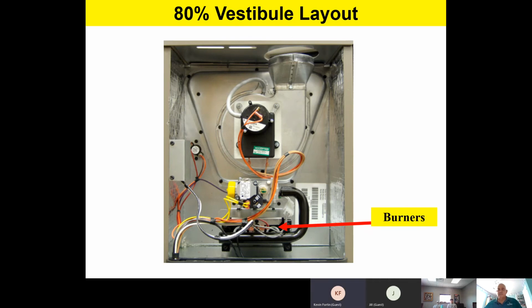Here we have our in-shot burners. Now it should be noted that all of our Champion products feature in-shot burners. On a propane conversion, please make a note of this. If you're going with a propane conversion, we do have stainless steel burners available, and we recommend that if you do go to a propane conversion, to go ahead and add the stainless steel burners as an accessory, because I think the stainless steel burners hold up a lot better, especially with propane.